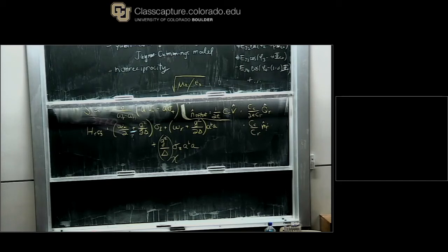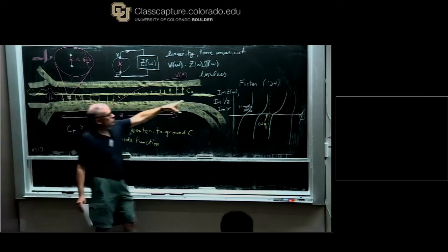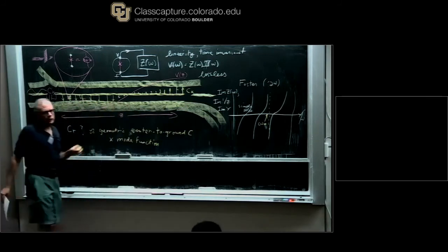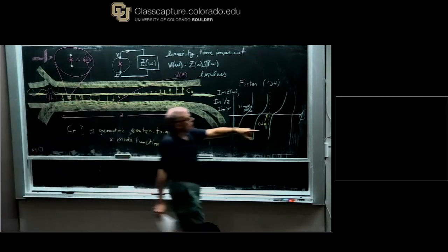which goes as follows. You send a tone in at the nominal frequency of this resonator, which you know ahead of time or you've measured already, and you study, for example, its transmission properties, although it can actually be its reflection properties. Now, it will not actually be the resonant frequency of this resonator.